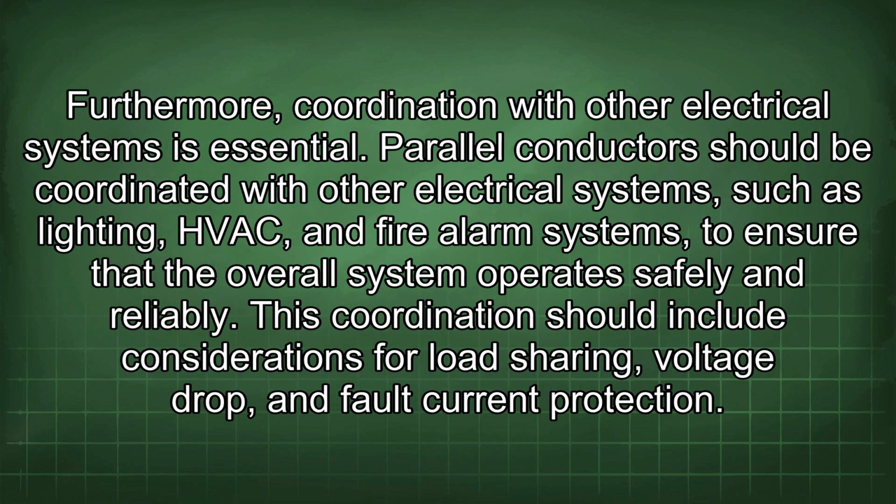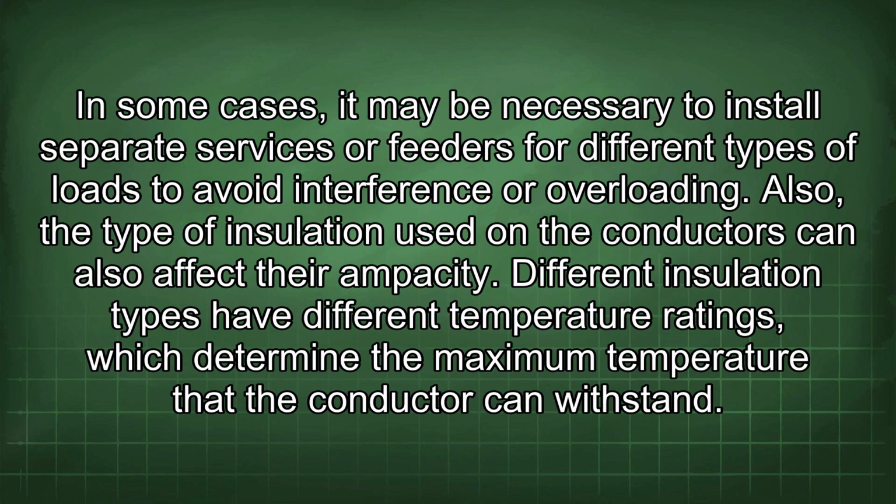Furthermore, coordination with other electrical systems is essential. Parallel conductors should be coordinated with other electrical systems such as lighting, HVAC, and fire alarm systems to ensure that the overall system operates safely and reliably. This coordination should include considerations for load sharing, voltage drop, and fault current protection.